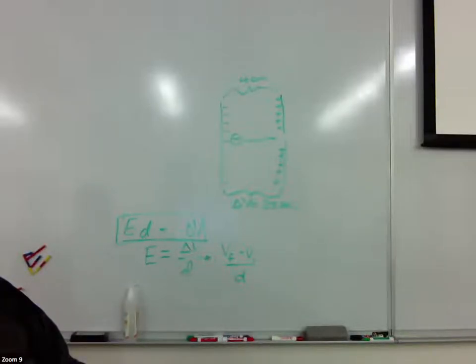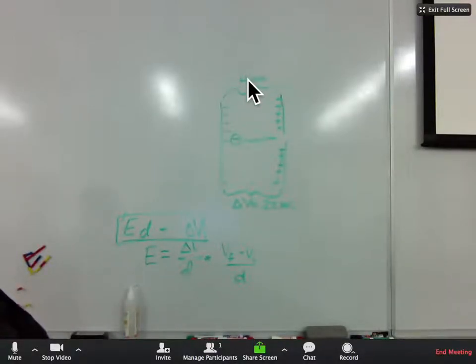But it's at a couple hundred volts. It's not going to strike lightning, so it doesn't really matter. You can bury it underground. It's fine. But at thousands of volts, that stuff will strike right through rubber and right through people and right through everything else. So you've got to be careful. You've got to put it up high so it doesn't strike down. All right, so that is that.